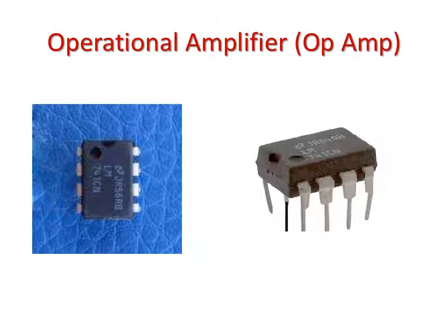For instance, some op amps have a very set operating voltage range. The MCP6004 only operates at a maximum value of 7 volts between the low end and the high end. So if you try to do minus 15 volts to a positive 15 volts on it, you're not going to get your ideal signal out. As a matter of fact, you could blow your op amp pretty quickly. The LM741s have a higher range for that. Usually, I believe they're minus 15 to 15, although again, you're going to want to look at the data sheet for that. Also important about op amps is the total range that they have and the amount of power that they consume.